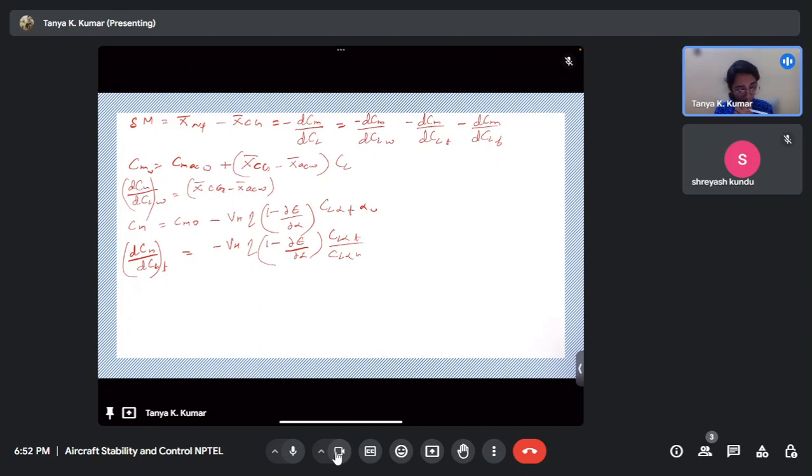Now let's do it for the fuselage. It's just that component. We haven't studied any expansion, so it's just dCm by dCl of the fuselage. Even in the options it is given in that manner, right? So now just put it all together in the equation for x bar np. I'm taking Cg on the other side because we need to find np.